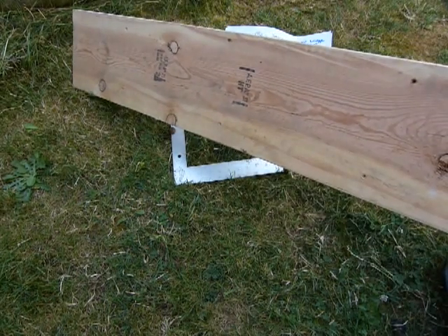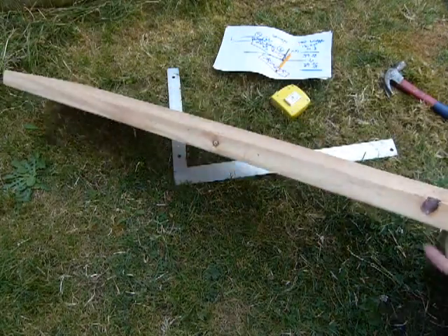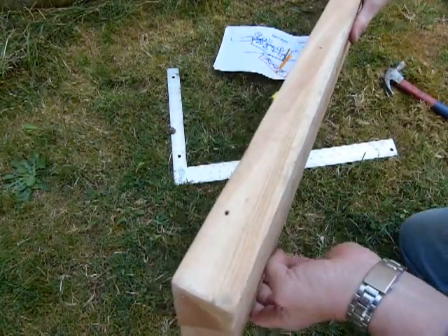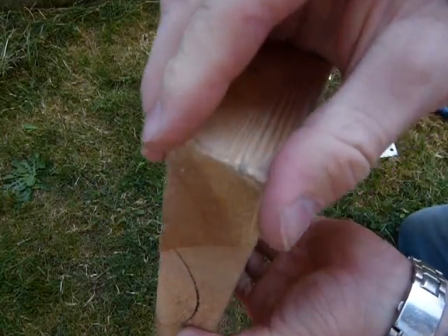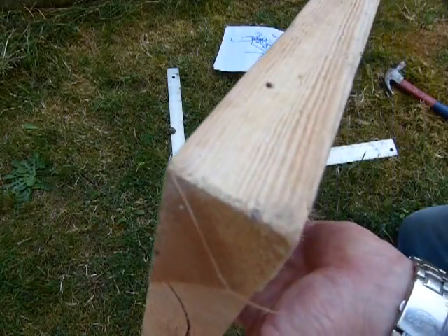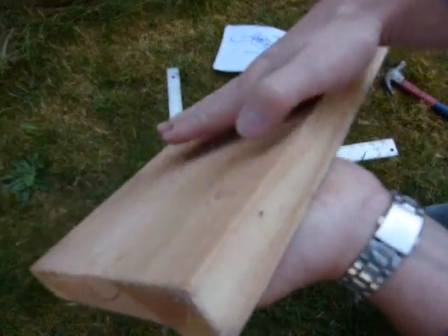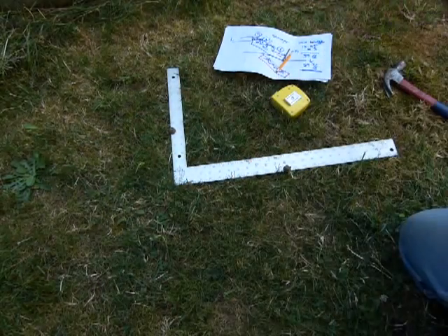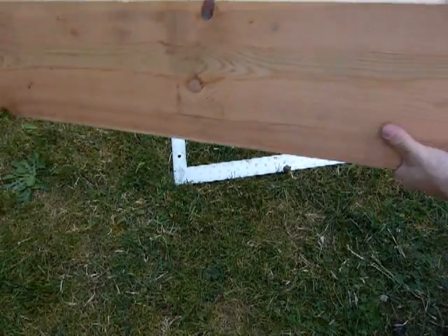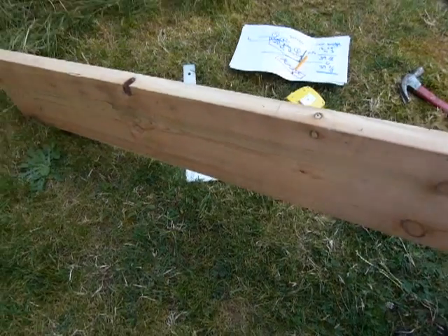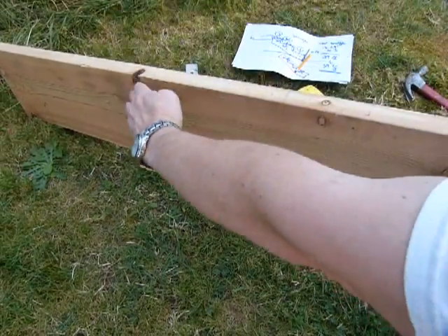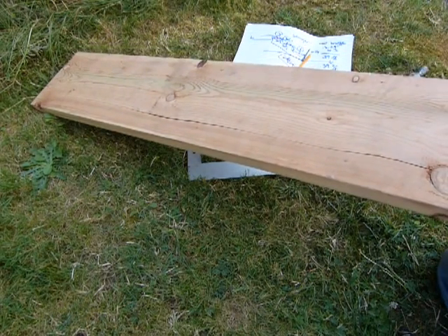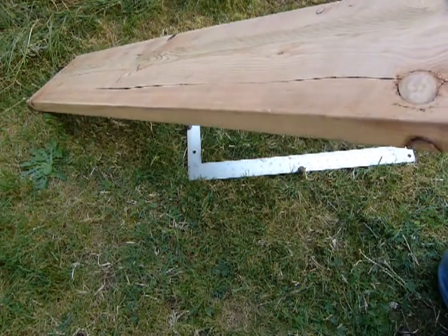You should choose a piece of wood that's straight when you look into it. That would be this direction for the camera. You look into it, you lift it up to your eye, and it should be straight. It shouldn't be warped, it shouldn't be cupping. It better not have a camber, which a camber would run in this direction. And most importantly, take a look at cracks and knots.